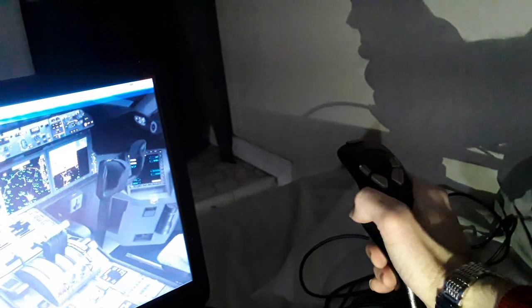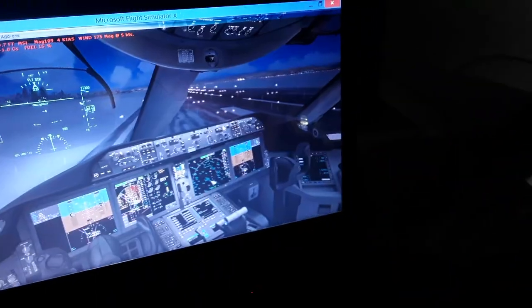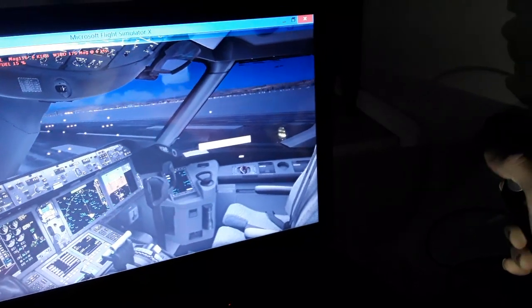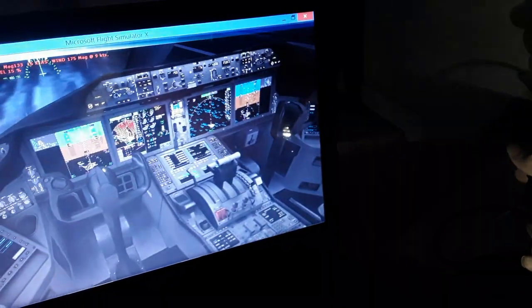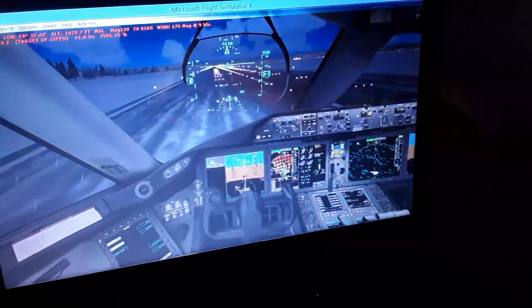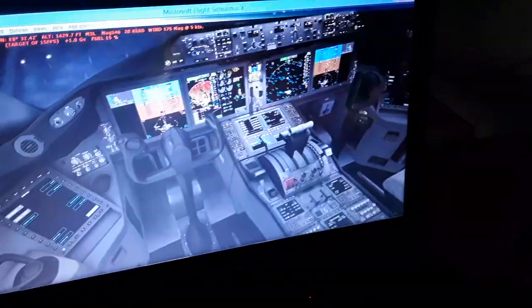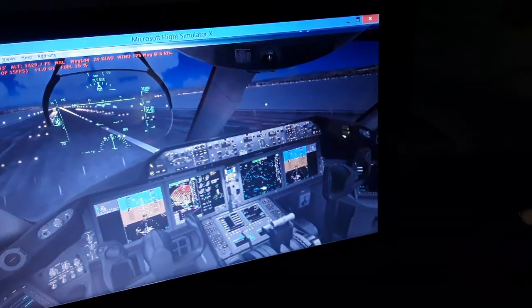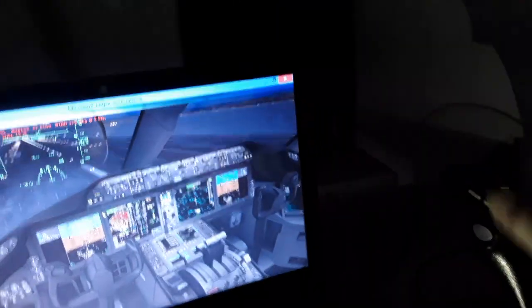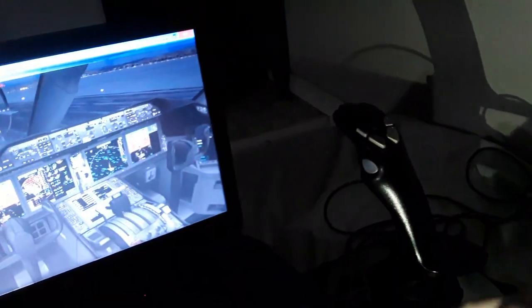So we advance again the thrust levers, need to taxi with alignment in the center line and the heading of the runway, 136 degrees. So this is how we align with the center line. Advance the thrust levers to full takeoff.